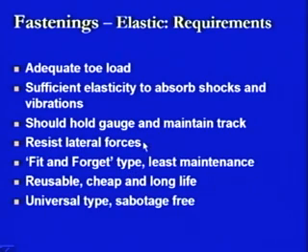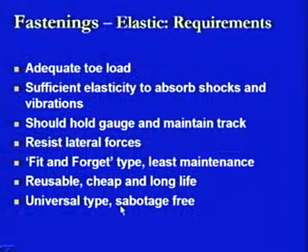Then another thing is that they should be universal type and should be sabotage free. That means a person should not be able to take it out as and when they feel like doing so, especially in the case of those tracks which are passing through remote areas where safety provisions are not, or cannot be, taken up. So, they should fit into the overall system in such a way that it is not easy for anybody who is not a skilled laborer, and does not have the devices, to take them out for maintenance purposes.